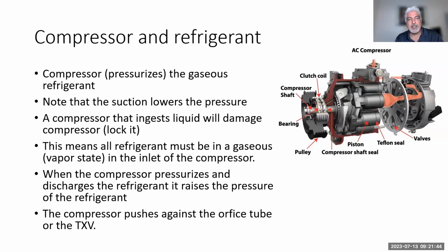So when I talk to guys that are building custom vehicles and they want to put AC in, I say, get a variable displacement compressor. Those are the ones where you won't feel the surge of the compressor kicking in and kicking out when the pressure goes either high or low.